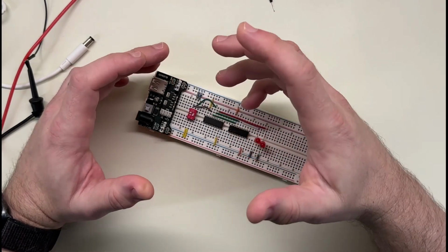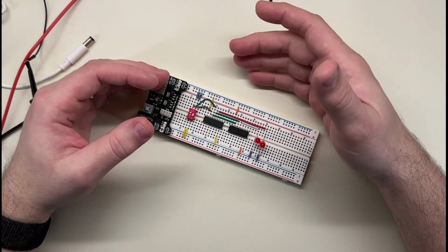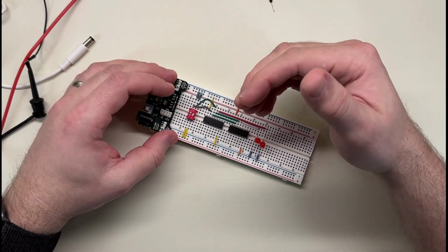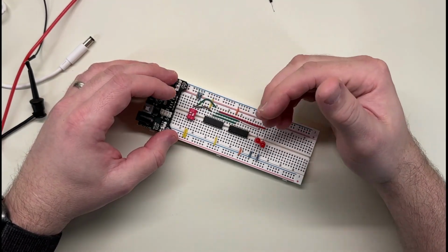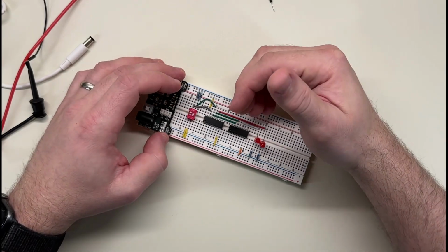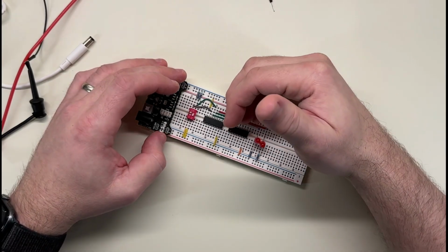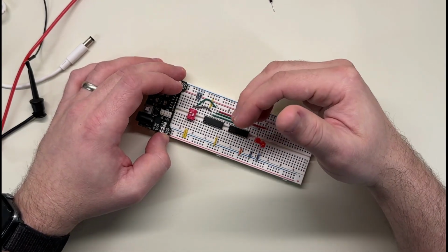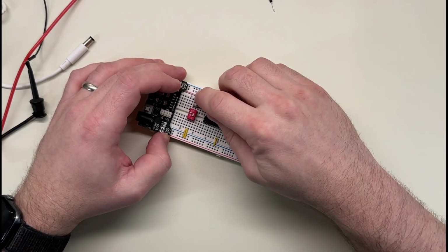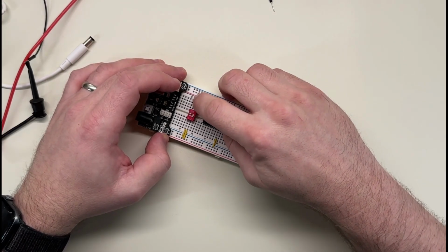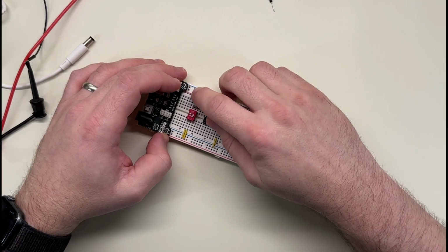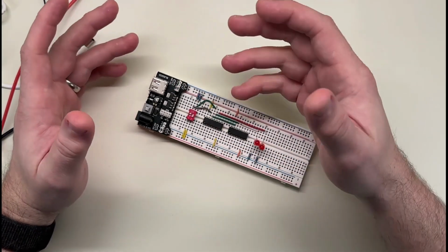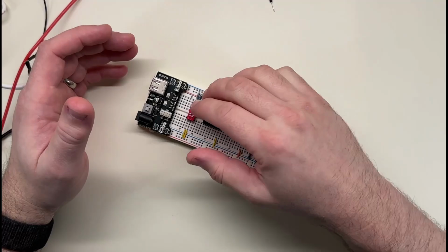And of course, I was thinking I want to optimize for that, get the lowest possible voltage level so that it's as close to false as possible, that would be the best thing to do. But what I wasn't thinking about was that a lower resistor means more current is going to flow. And current is your energy usage, right?